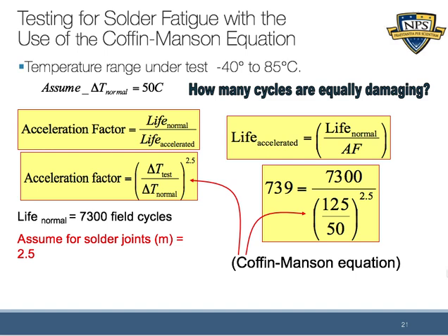And it's important to know that the delta T of 125 here is somewhat arbitrary, right? It could be chosen to be 120 or 110, or even maybe more, 150, 200. What's important, though, to understand is that your temperature chamber, whatever test chamber you have to test this in, could potentially be the limiting factor on that.